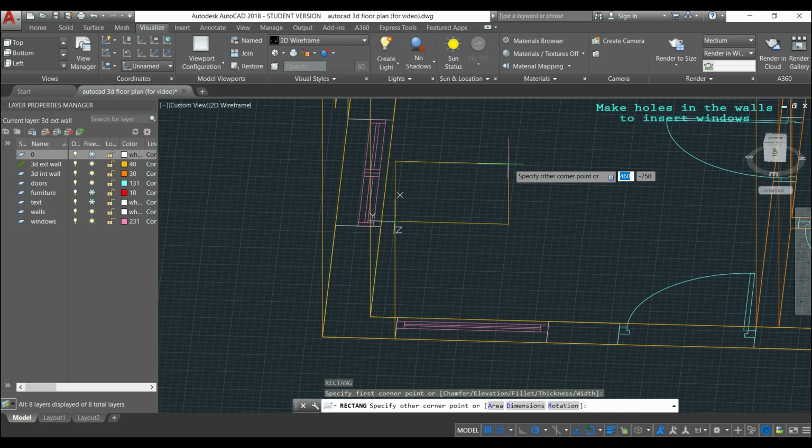This means that for this window the x-axis is now the vertical dimension, and I'm going to type now that distance, which is 1200. Then I press tab, and then I have to insert the distance in the y-axis. If you look to the drawing, you will see the y-axis is in opposite direction against the horizontal length of the window. Thus, I have to type minus 1000.